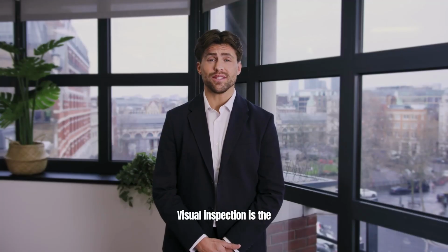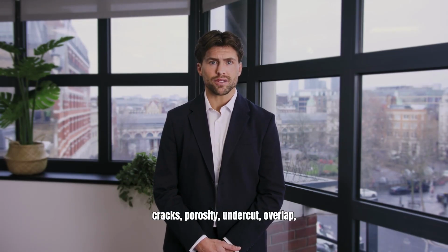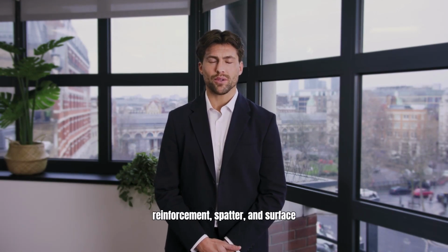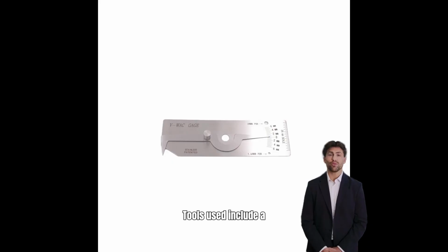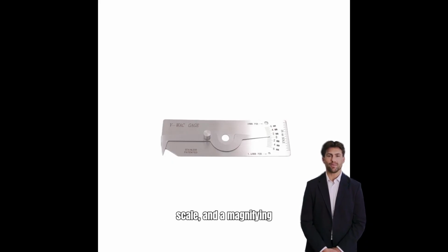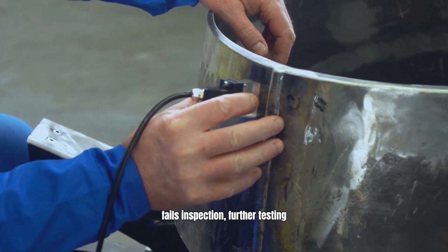Visual inspection is the simplest and most common method. The inspector checks for cracks, porosity, undercut, overlap, lack of fusion, excess reinforcement, spatter, and surface finish. Tools used include a welding gauge, torch, measuring scale, and a magnifying lens. If the surface itself fails inspection, further testing is done.